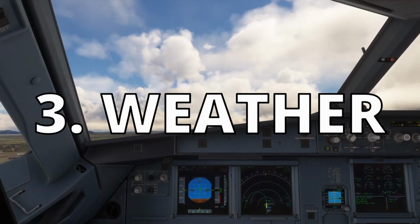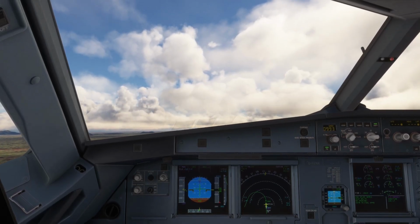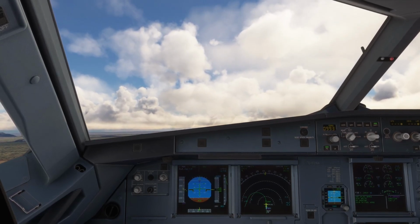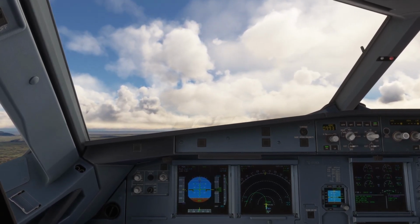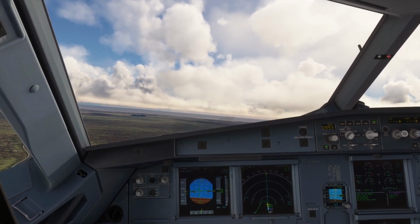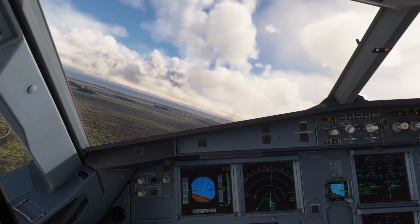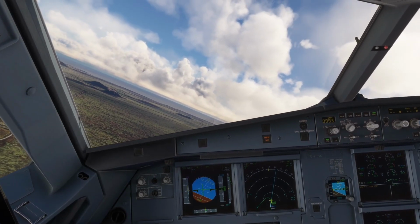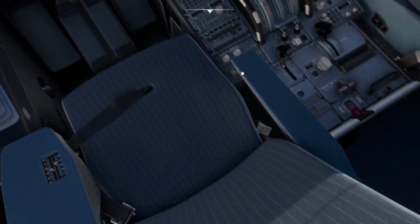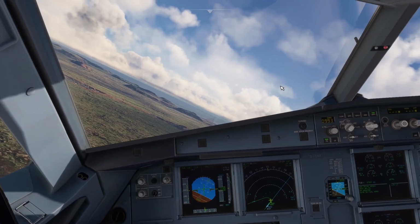The third thing is miscellaneous stuff like weather, and other stuff like proper precipitation, low visibility operations, contaminated runways. So you need to know what the braking action figures in the ATIS actually mean. Icing conditions, towering cumulonimbus clouds that you actually have to deviate around. If not, you're going to get severe turbulence, wake turbulence, even for some simulators. And some add-ons like the Phoenix A320 even simulate compressor stalls or high engine vibrations if you don't do proper ice shedding procedures.